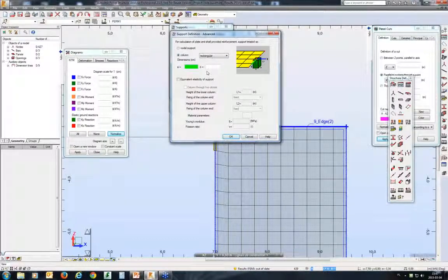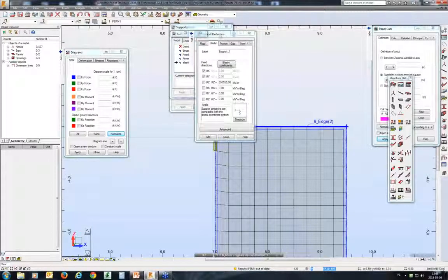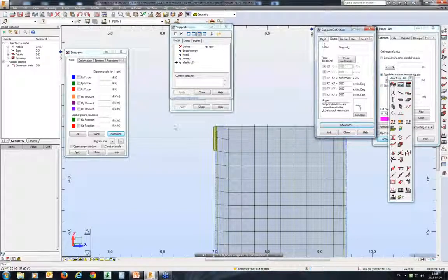No, not really. I mean, you remember this slide where I put the comment, do not try to be as accurate as your architect is? That was just intended to show this rigid link. But for example, if that was a steel beam, let's say you've got a 4-meter wall and a 200 millimeter steel beam, I would definitely define that at the top of the node. So this beam would go at the top edge of the wall.